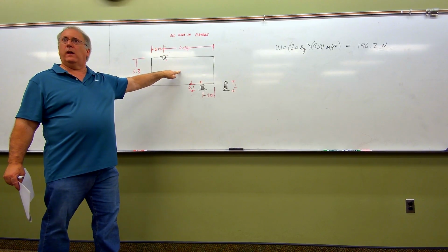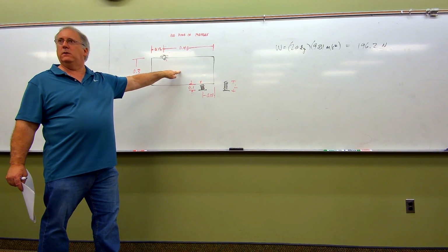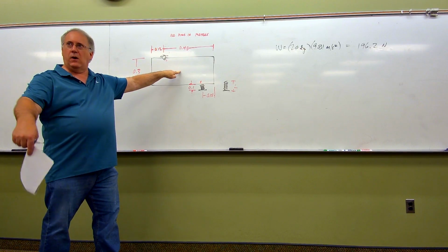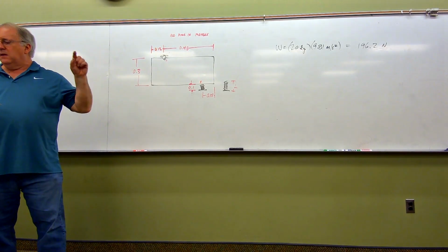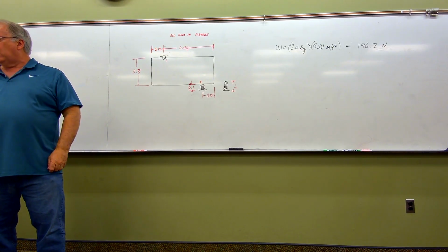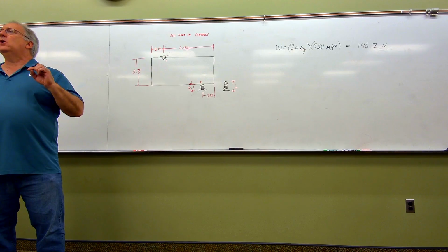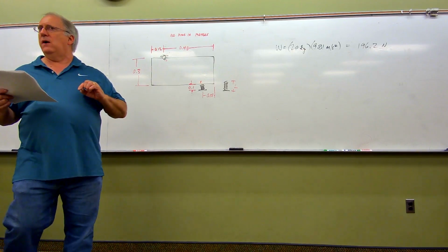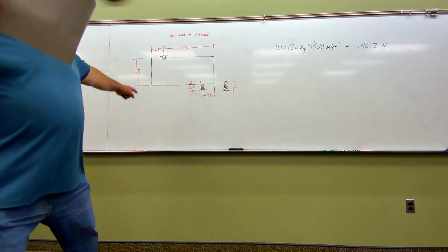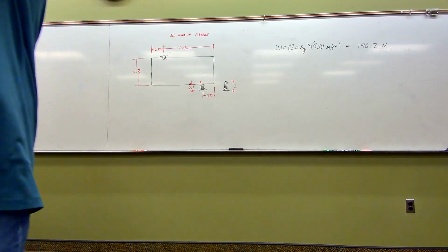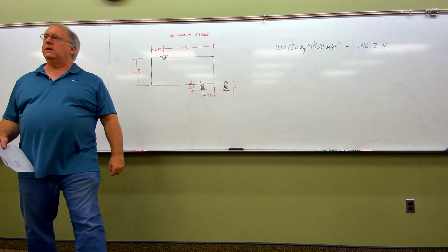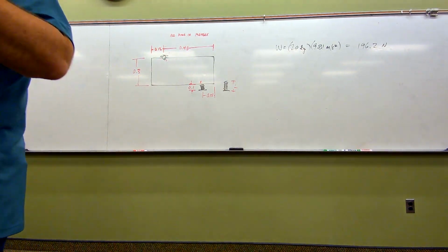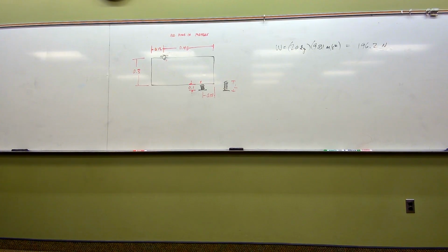And by the way, where does weight point? Straight down towards the center of the earth. So we know where that weight's going to be. Then hear these words again: supported by, quote, an ideal pivot. What's that word ideal telling us about the pivot? Exactly. So up here at point O, this so-called ideal pivot can also be read as frictionless, smooth. We use these words kind of interchangeably throughout here.